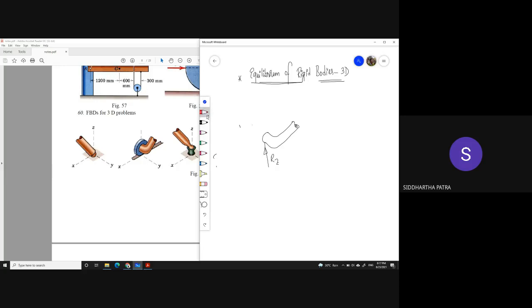Okay, it cannot move vertically downward. Therefore, there is a reaction force coming from the z direction. Also, because it cannot leave the channel, you can imagine the two ends of the channel are slightly protruded vertically. So there is some reaction force in the y direction as well, preventing the object from leaving the channel. Simply, it cannot move along the y-axis.